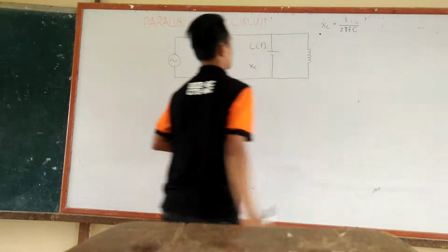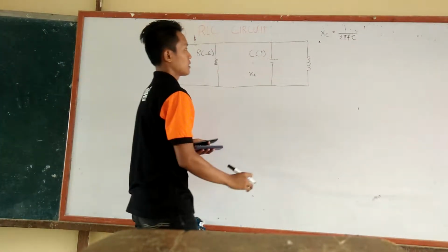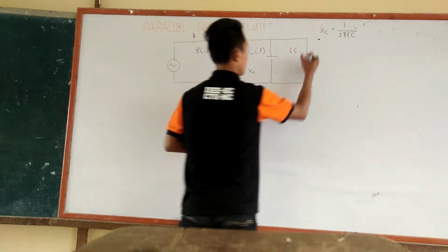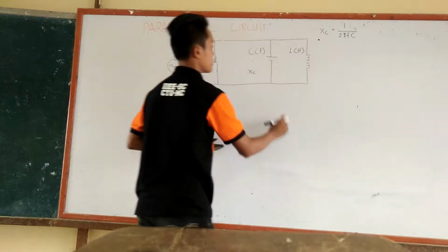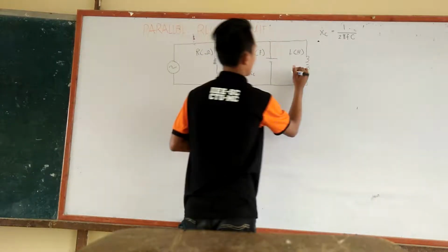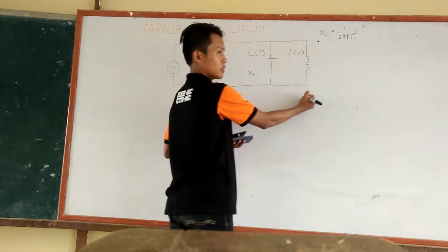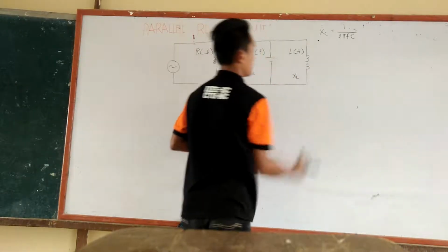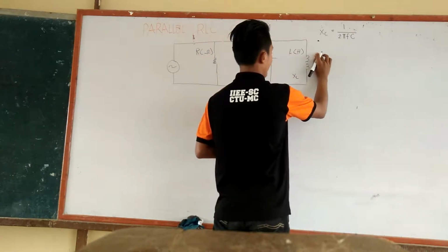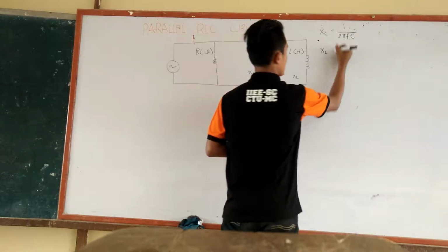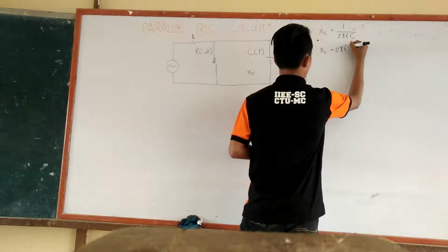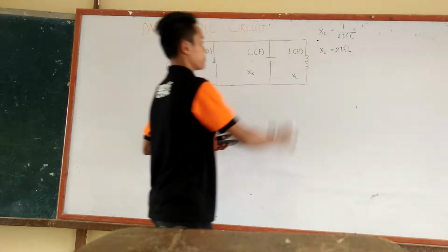capacitor in farads. Our inductor will be labeled as letter L, and it is measured in the unit of henries. There is an opposition here also, which we call the inductive reactance, labeled X sub L. And from our previous discussion, this is the inductive reactance that can be solved using the formula 2 times pi times the frequency times the value of the inductor in henries.